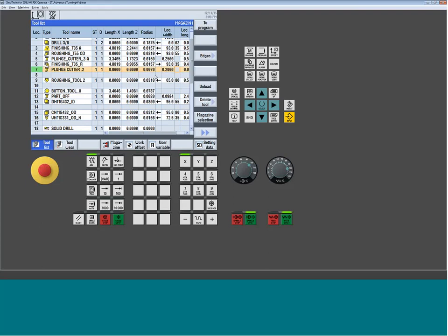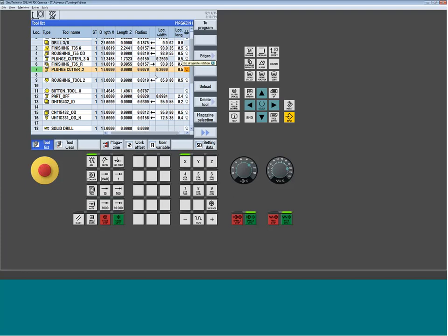Now you don't have any relief angles or anything here because it knows that it's a rectangular type of geometry, but you do need to go give it the length of the insert. And the length of the insert's not that critical. It's really just for the graphic representation of it. So if I tell it it's a length of a ½ an inch and I send that grooving tool 1 inch deep, it'll let it go. We're not limiting your depth based on this. This is just to kind of create the picture of the tool more than anything else. It doesn't have a lot of other bearing on the part program. But I build the groove tool. I tell it to the program.